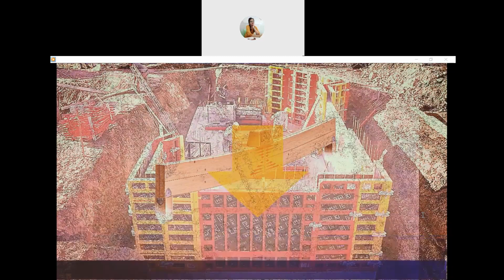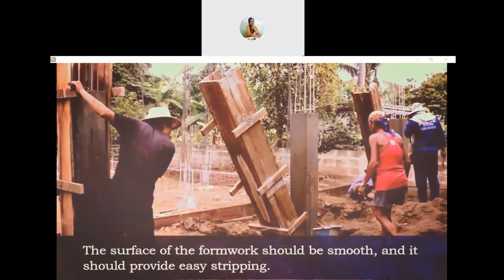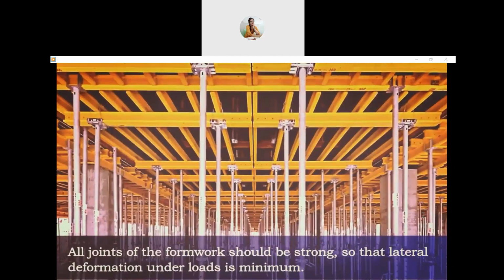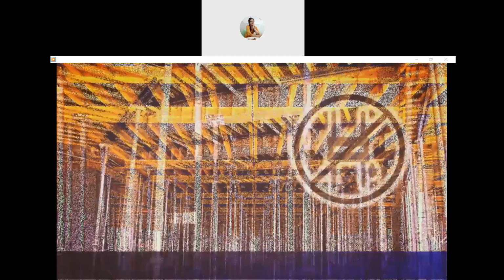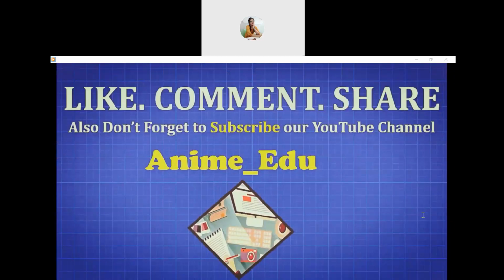The surface of the formwork should be smooth, and it should provide easy stripping. All joints of the formwork should be strong, so that lateral deformation under loads is minimum. These joints should be leak-proof. These are the requirements of good formwork.